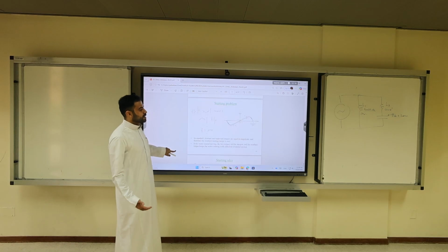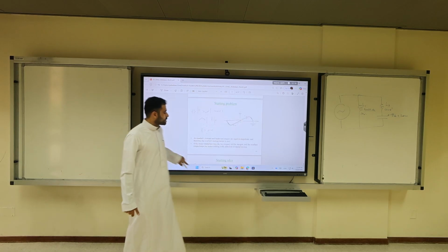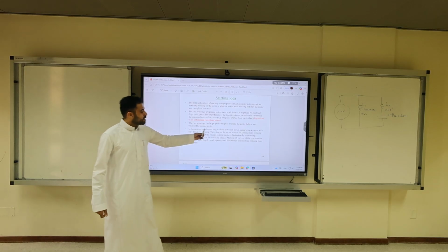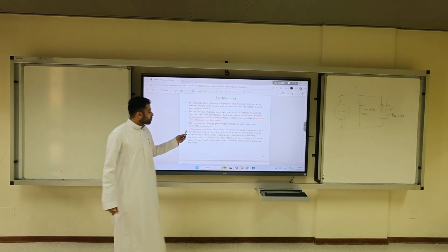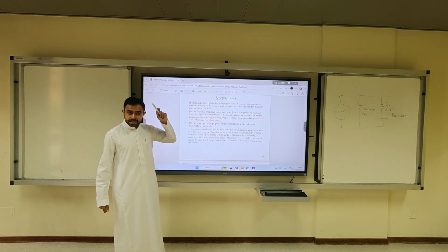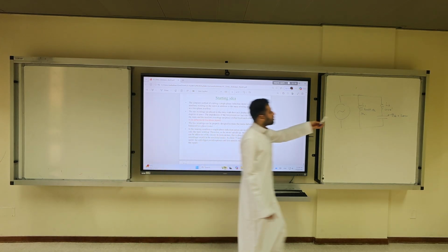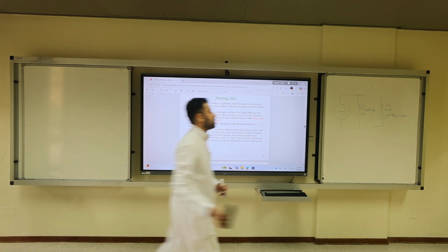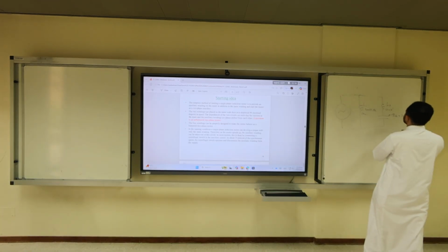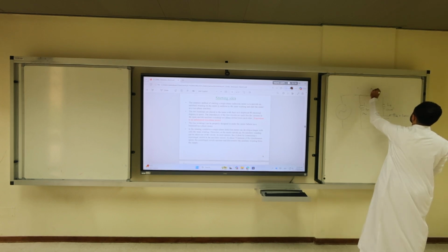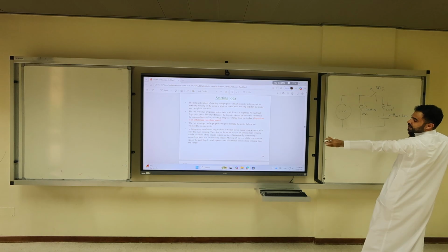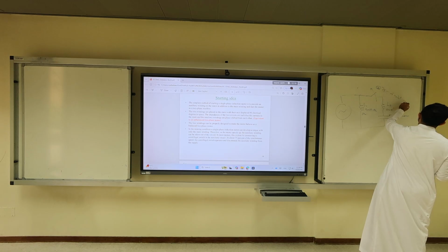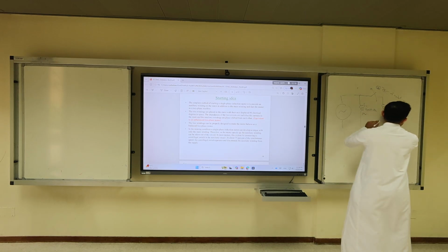But this is still not good because it doesn't make sense to keep both every time. And what did we say the starting idea was? The starting idea was, in the running condition, we can develop a torque with only the main winding. In the starting condition, you include the auxiliary one. And we said, at some point, at 75% of the rated speed, open this breaker. We still didn't talk about the capacitor.